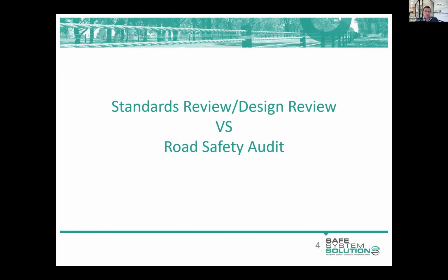Any road project brings together all sorts of different design elements, and it's a particularly dangerous situation, or potentially dangerous, when we're combining various minimums. So a road safety auditor really needs to look beyond standards. It's possible that something is in accordance with standards and is not safe. And similarly, it's possible that something doesn't meet standards but might be safe.